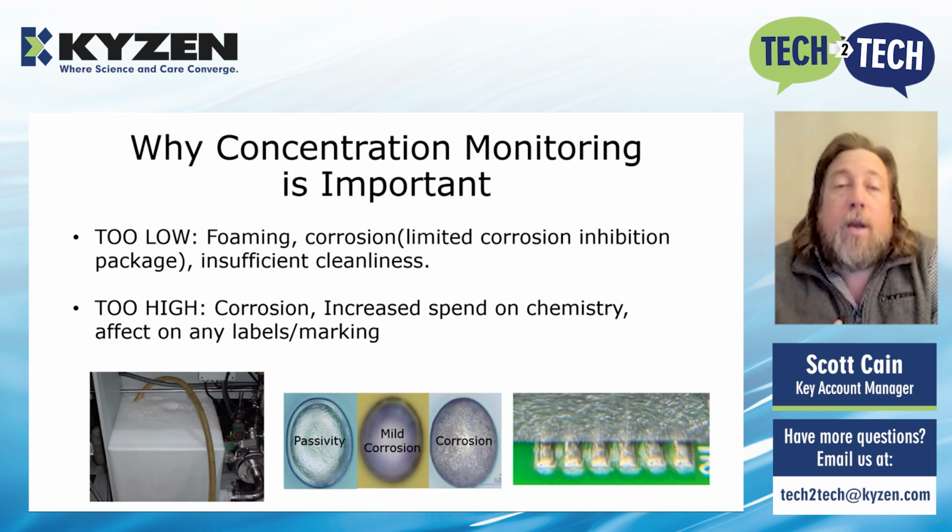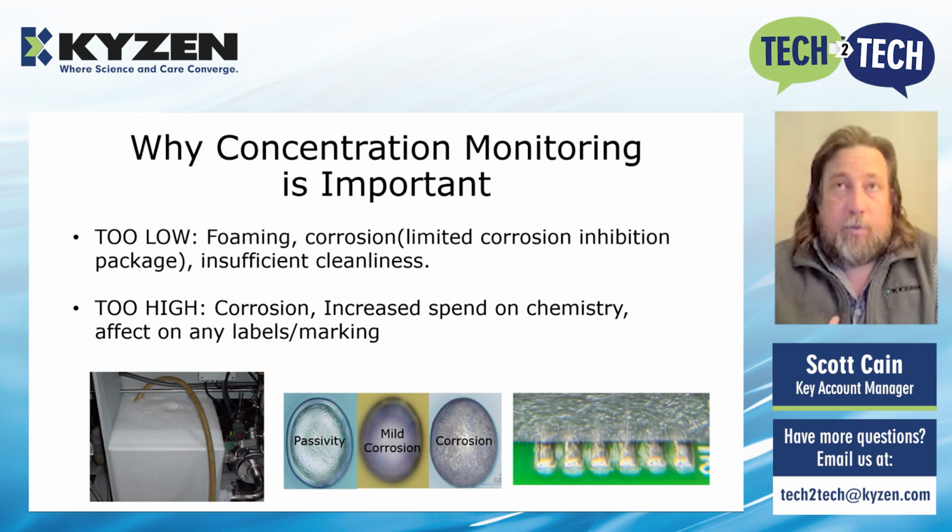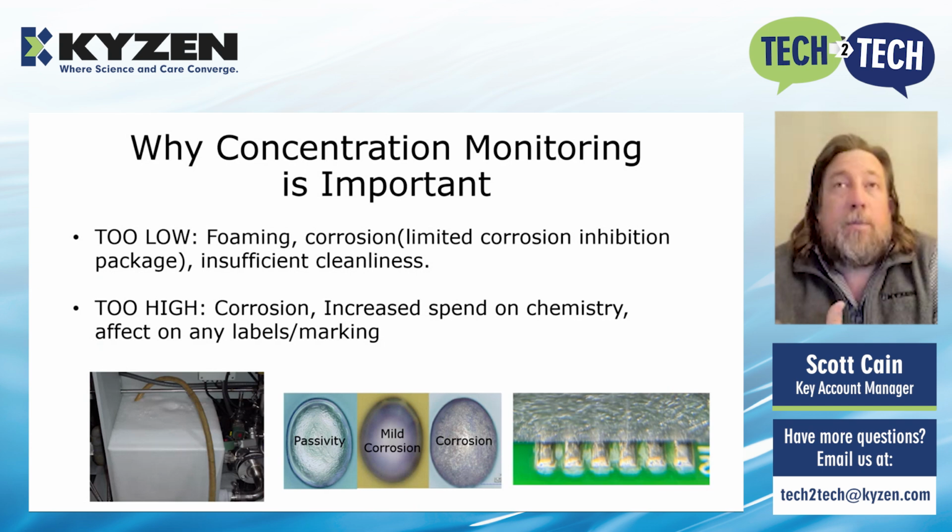But on the other end, we don't want to go too high, right? We talked about the corrosion. You're going to be spending more on the chemistry. The chemistry costs money. We want to make sure just the right amount is used. If the concentration is too high, you're using too much chemistry to get the same cleanliness level that you can get with the chemistry that's within the range. And it can have an effect on any of the labels or markings that are on the parts. It just becomes tougher for those to withstand the cleaning process. So that's why we want to make sure we have that concentration monitoring dialed in.